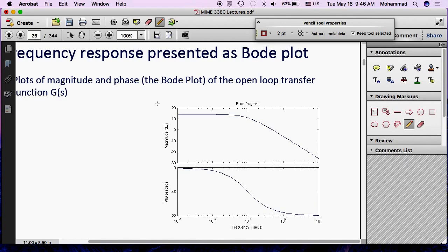On the horizontal axis, it's again frequency. At the bottom, it's a phase shift. If you move your input at a certain phase, would the output follow, or lag behind, or be ahead of your input? That's what that shows. And hopefully we'll get to more. Any questions on what this is? So what does this tell you? It tells you, for a linear system, the ratio of input and output is constant at low frequency. And then as you get to a higher frequency, that ratio drops.